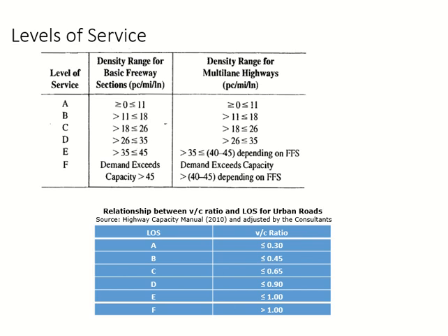This is another way of calculating level of service. They use it in the ministry as well. Instead of using density, they are using volume upon capacity. So find out the capacity, find out the volume. I already showed you the equations. You can take the ratio, and the ratio will give you the level of service. So level of service A is up to a volume capacity ratio of 0.3. More than 0.3 up to 0.5 it's B, and so on.